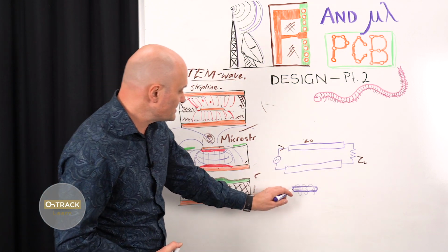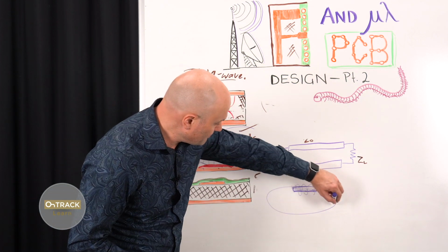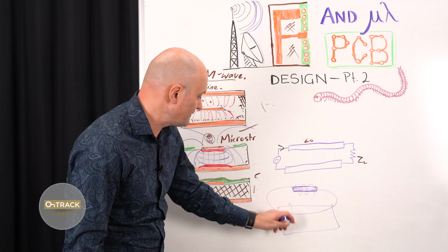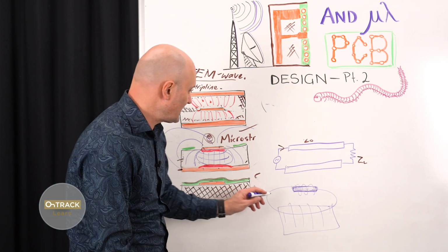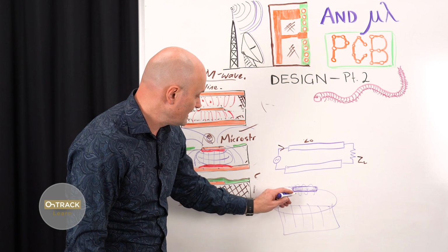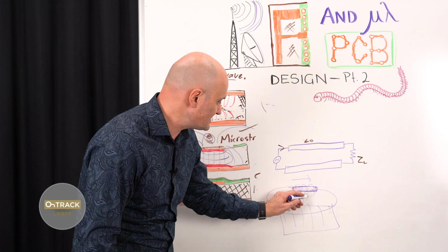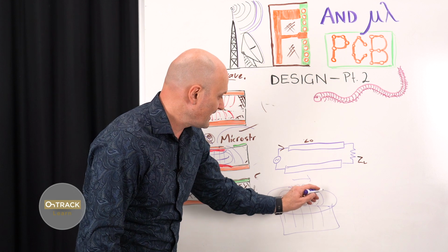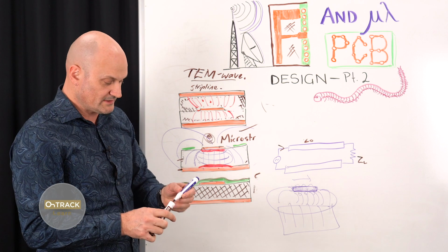Also, with the transmission line, we know current has to flow in loops, and in a PCB, and particularly at high frequencies, we have a reference plane, which is presumably at 0 volts, and then we apply an AC signal to our transmission line, and as it travels down the line, it has to charge up the capacitance between the PCB trace and the ground plane, and then it gets to the load, and that energy is transferred to the load like a bucket brigade delay line.